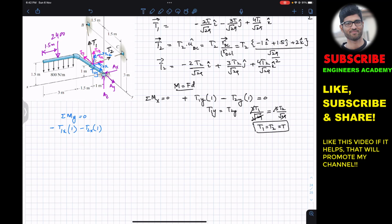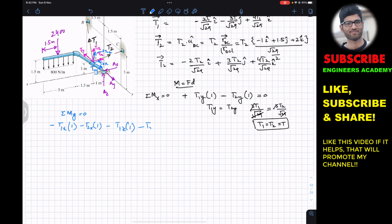And again T1z and T2z are going to produce a moment about the y-axis in the clockwise direction as well. So we will write minus T1z, and the perpendicular distance of T1z and T2z from the y-axis is 1 meter. So we will multiply T1z with 1, and similarly minus T2z into 1.